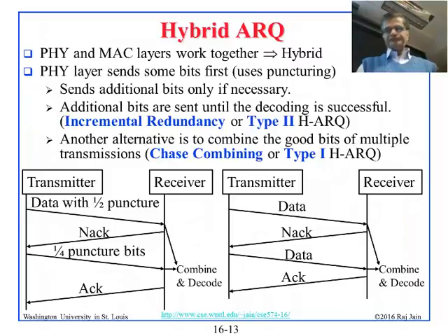Yeah. Is it generally considered bad practice to combine layers like this? Okay, all right. No, hold on. So this is, layering has advantages, layering has disadvantages. So the advantage of layering is that when you're designing MAC, you don't have to worry about PHY. You can design your MAC as it is. And you can design your PHY without talking to the MAC guys. Now, having said that, that's the advantage, the design time.